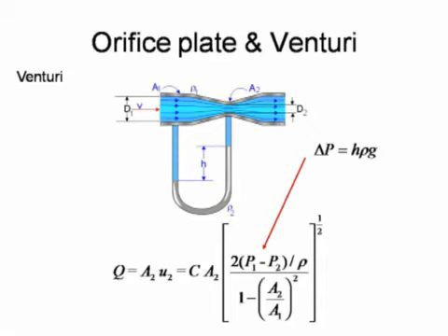flowing through the system, which is kind of a difficult concept, because that means we're measuring the manometer height, h in the diagram, in terms of height of the liquid that's flowing through the system. Of course you wouldn't have an interface there, so if you do that substitution, it's kind of an imaginary height of liquid in a manometer, whereas in reality you might, for example, be using mercury to measure the pressure difference of the process fluid water. So the height will be different because mercury has a much higher density than water. It's probably safest to leave it as P1 minus P2 and not to make that substitution unless you really know what you're doing.